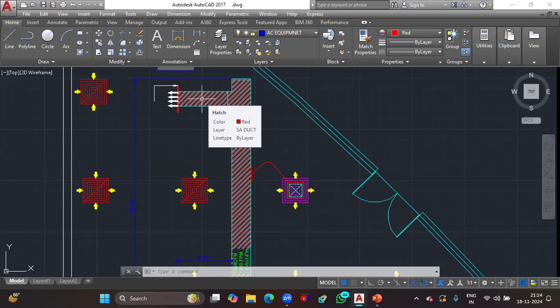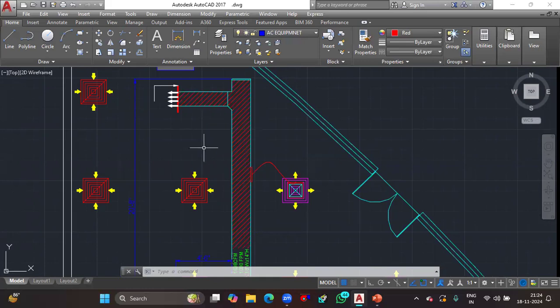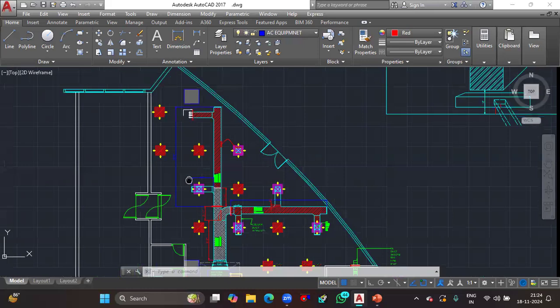In fan selection, we need to constrain the farthest air terminal from the mouthpiece itself. Is my point clear? In a complicated ducting, a lot of branch ducts and collar ducts go across your floor. But the constraint that we need to consider is very simple. You need to consider a flow path from the machine mouth to the farthest air terminal. So how do you calculate your farthest air terminal? That is the concept.